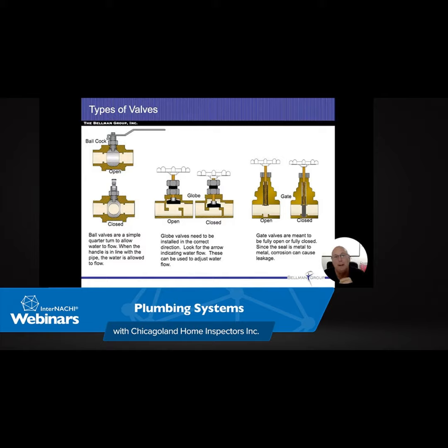Hair is a huge one, especially if you don't use that appliance for a while. So if you get hair that's caught in the drains, and it doesn't necessarily have to be in the trap, it could be anywhere down the line, that acts as a wick, and it'll just keep sucking the water right out of there, just like a lantern would lift the oil out and move it right over.